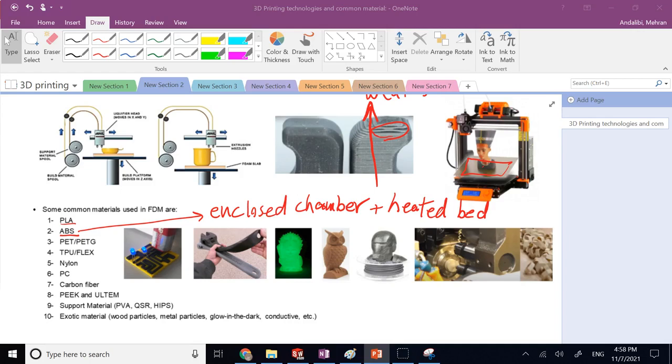Now, before I go to PETG, similar to PLA, ABS is, as I said, a little bit stronger, more impact resistant, but again, it's not super strong. Its toughness is not super high. If it falls out of your hand, there is a good chance this one also breaks, especially if it's not completely solid. If you want some part that is a little bit more flexible yet strong, so it's a little bit mechanically maybe better than both of these, that's PETG.